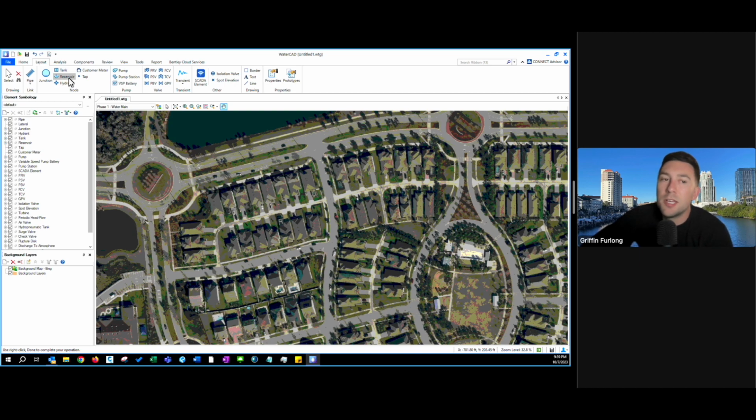I'll get into the nitty-gritty of a reservoir and pump later, but for now, I'm going to model a point of connection. And in this case, we're just going to throw a reservoir. Think of the reservoir as a certain pressure that you're tying into. I can actually set an HGL, or hydraulic grade line, of this reservoir. So I can actually simulate a static pressure. And again, this will just be a static pressure condition.